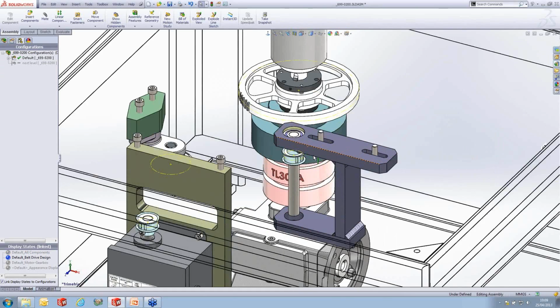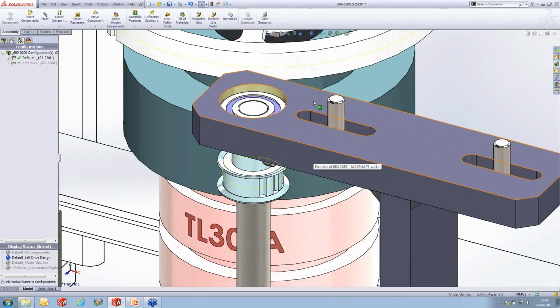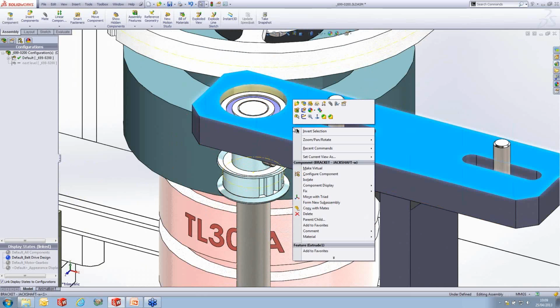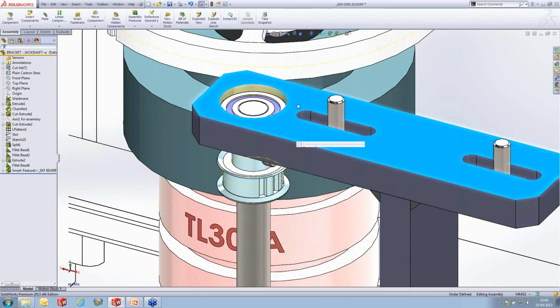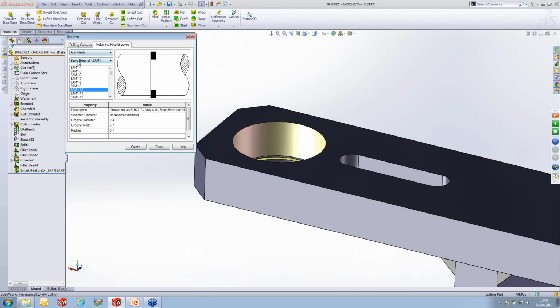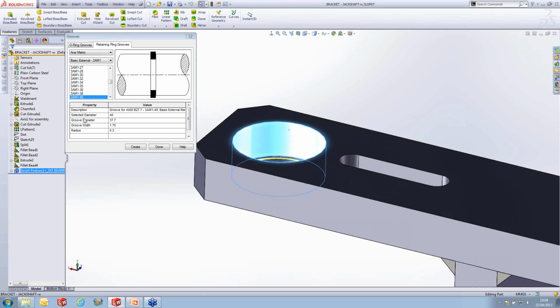model there. So I can zoom in on this section and I can actually insert retaining ring grooves and O-ring grooves around here. All I do is just open up the individual parts by clicking, and then we can insert maybe a retaining ring groove at this top section. So we go to the grooves menu, select maybe basic external. It's the same process. When we select a face to select the diameter, it will insert the item, if we choose internal, at a slightly larger diameter than what we've selected rather than slightly smaller.